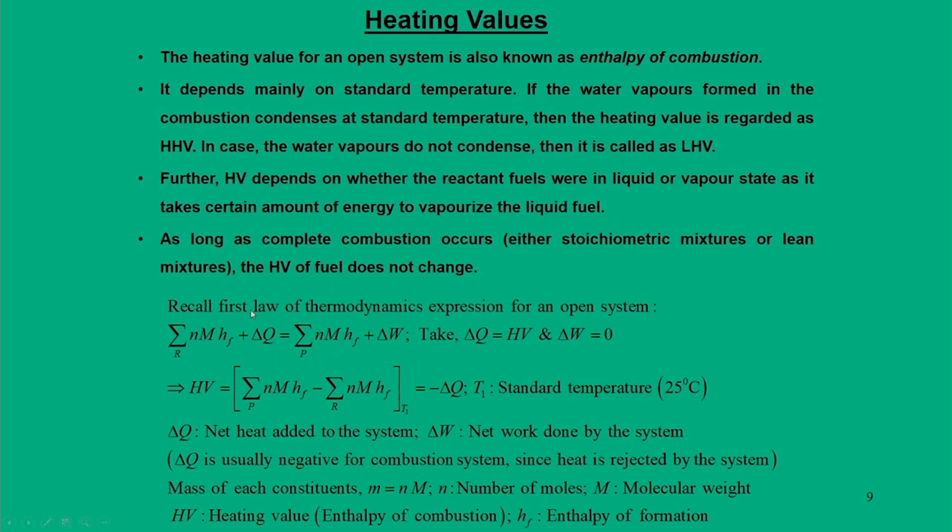Now, I have also explained that the heating value for an open system is nothing but the enthalpy of combustion, and we have higher heating value and lower heating value. A further point I need to mention is that the heating value depends on whether the reactant fuels are in the liquid or vapor state, because it takes a certain quantity of energy to vaporize the liquid fuel. So, as long as complete combustion occurs, the heating value of the fuel does not change.